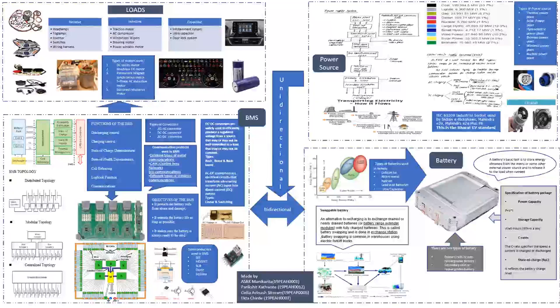Normally, as per the standard, type 2 is used for almost all electric vehicles in Bharat as per the Bharat regulations. It's IEC 62196. A 3-pin connector is also used for normal electric scooters. This is for the AC plug connectors.